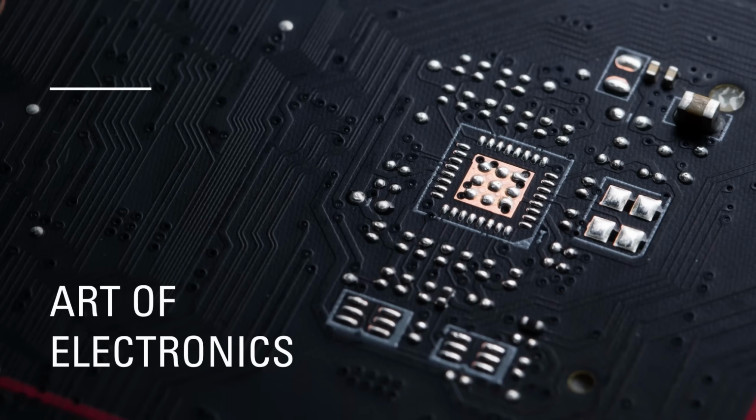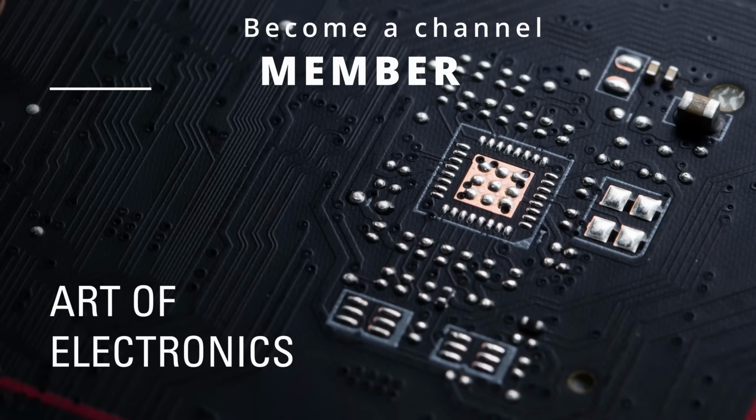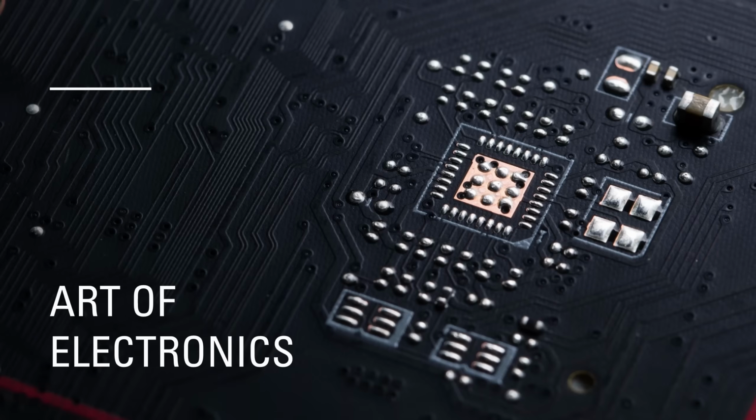When you first see exercise 3.2 in The Art of Electronics, it just looks like another maths problem, which seem to be very common in The Art of Electronics. But it's actually one of the key steps in understanding what a FET really is. This little derivation links the gate voltage, the drain current, and the channel resistance, the three things that define how a FET behaves. It shows that the same device can act like a variable resistor, a clean amplifier, or a switch, all depending on where you bias it.